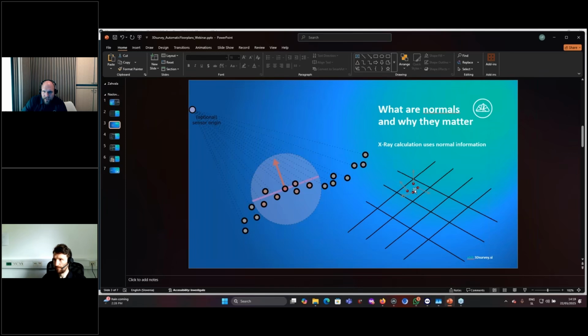If a point cloud has normals, 3Dsurvey will create white color only if the points falling inside have a normal vector which is close to parallel with this image. So the points which have a normal looking perpendicular to the image will be ignored.